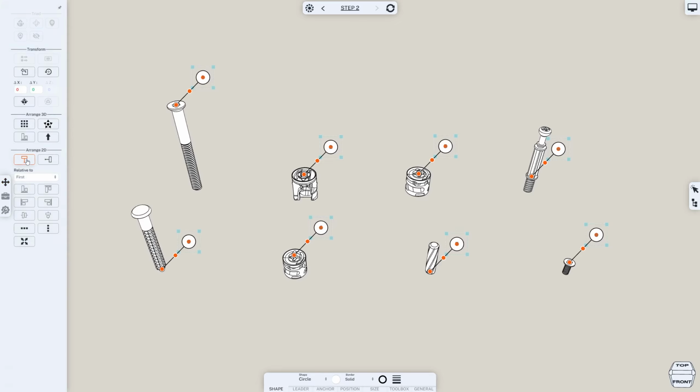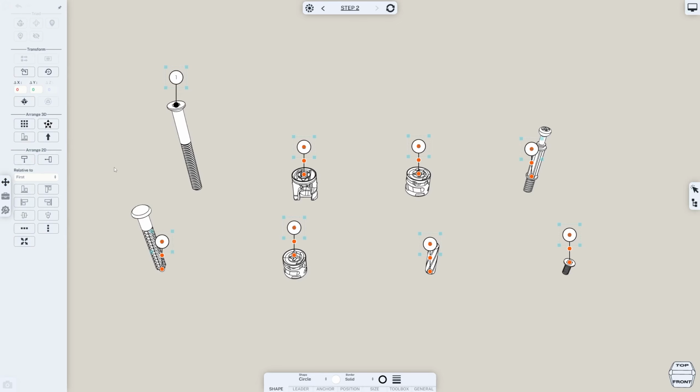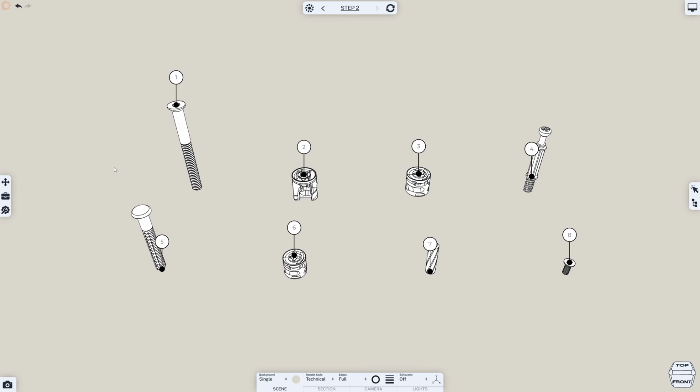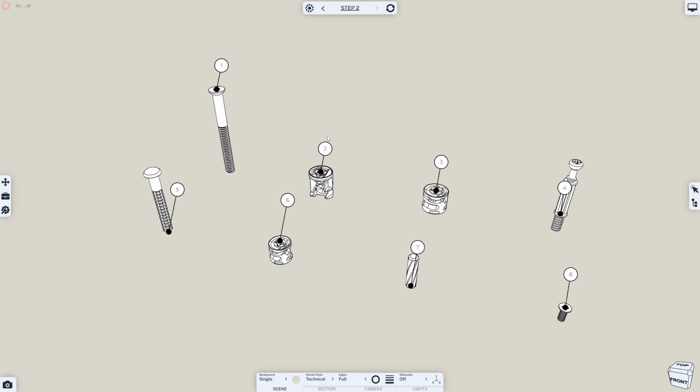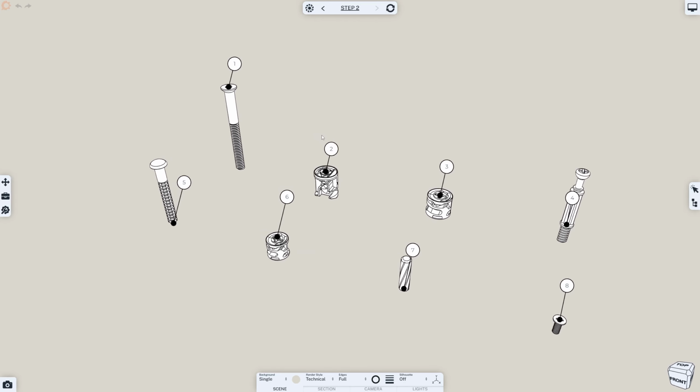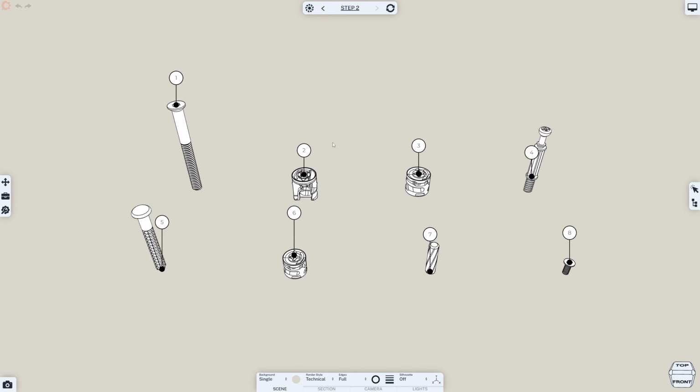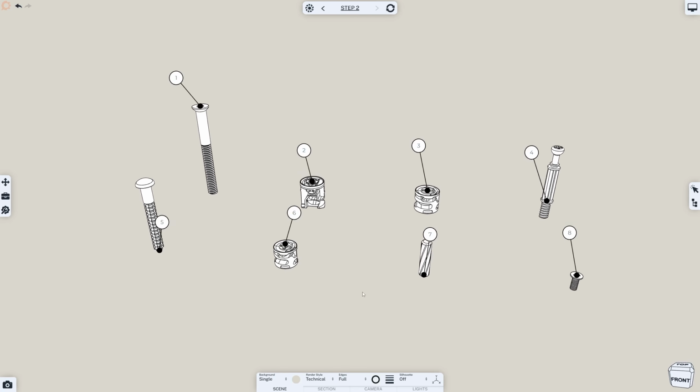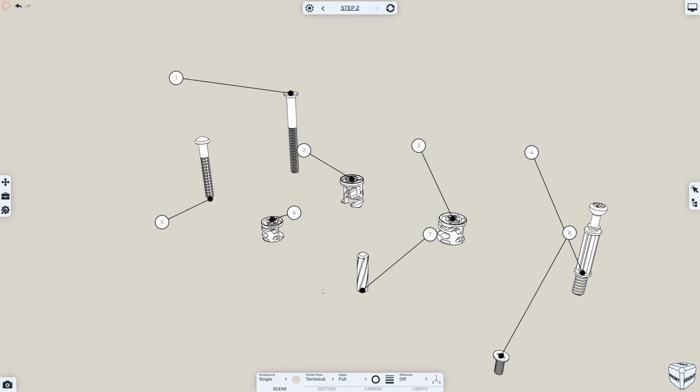The layout is now looking clean and well organized, but there are a few additional things we can do to finish off the step. When the end user views this step, by default they will be able to rotate the view. Often this is fine, but sometimes you may not like the way the 2D items move around. One option is to pin the balloons. This keeps them fixed in place, but the leaders will still adjust with the camera, potentially causing overlaps.